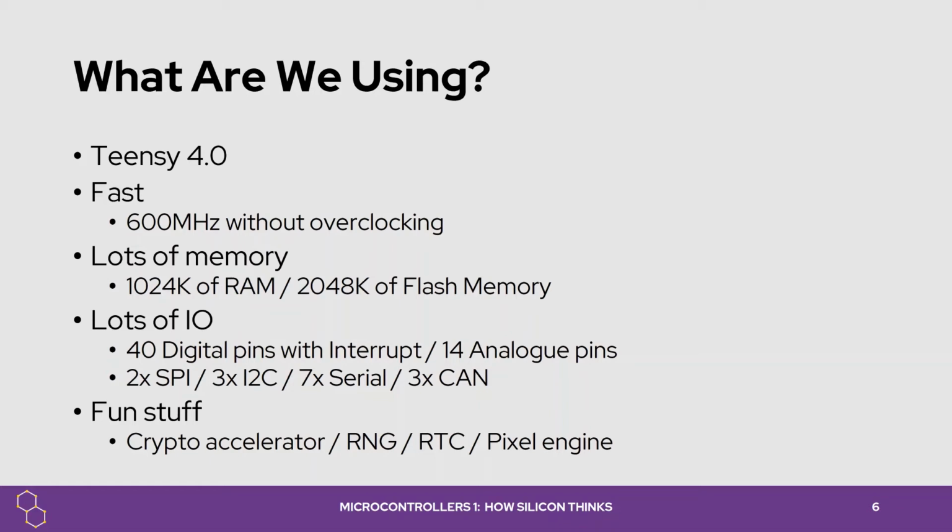That is a thing that happens on Arduino boards, where when you overclock your microcontroller, the internal hardware timers accumulate error. They stop being accurate because they were designed with a fixed clock speed in mind. The Teensy doesn't have that problem.